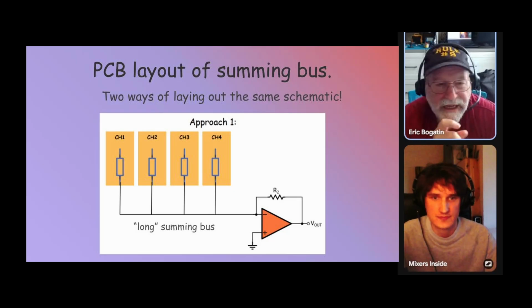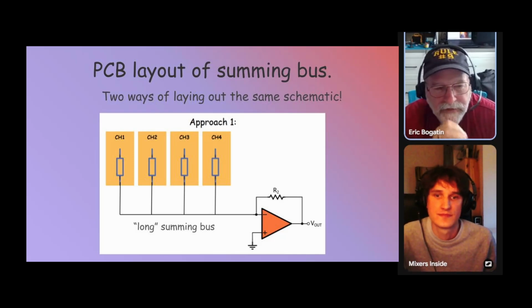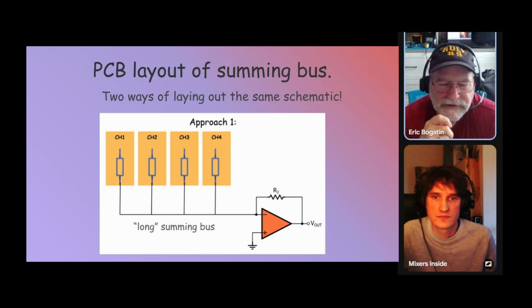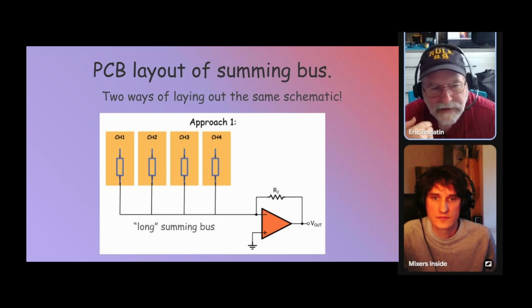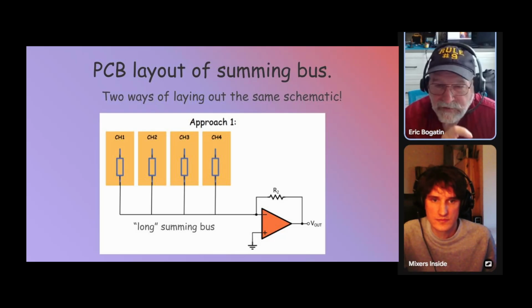So I don't think there's anything that can justify the single ground connection. Unless everything is differential. And if everything is differential, it's not so big a problem. The difficulty is that there are two kinds of noise that one of the analog channels is going to see. There is the noise from the digital channels because they're switching and they have current. And by itself, there's going to be a large amount of noise on that. That's the voltage noise between channel 1 and the reference ground connection. There will be a lot of noise on that.